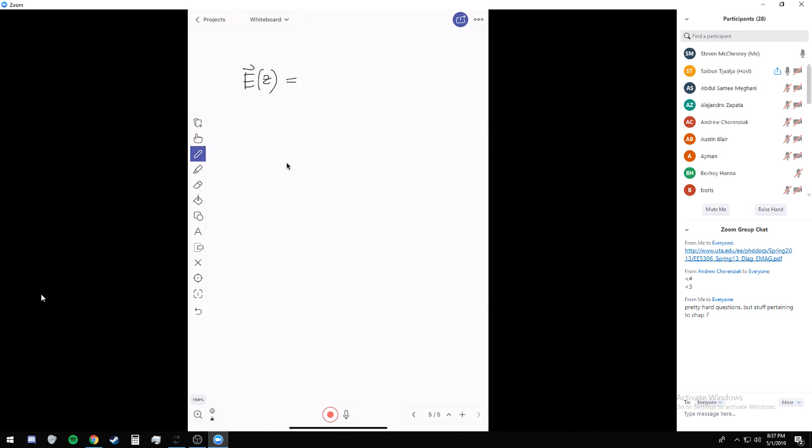Now if I give you more, for example, this is polarized in the y direction. Maybe I just put 10. So the amplitude is 10 throughout the xy plane, but all the electric field variation or fluctuation is in the y direction. If I ask you what kind of antenna can produce this, suppose you say dipole, suppose my dipole is infinitely long and oriented toward the y direction, and then we have e to the minus j k z. Of course, if I tell you the frequency, permeability and permittivity and assume it's lossless, then k is fixed. k is equal to omega root mu epsilon.